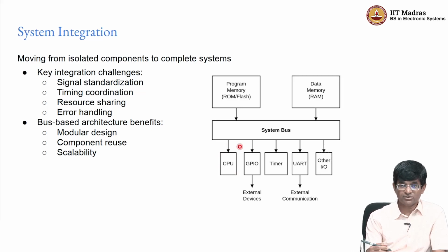And in fact, in terms of the sheer space occupied, in some sense this is true, except that of course the CPU in modern practical systems is not as small as what it looks over here, and the bus is not really a very big physical device. The reason why it looks big is because there are many wires that need to go across over here, plus there are of course the multiplexers, decoders, and so on that are associated with the bus activity, right?